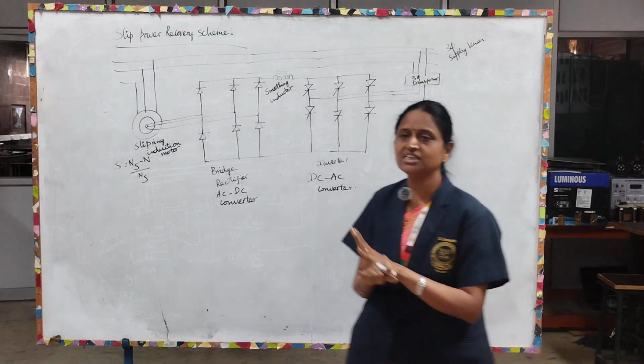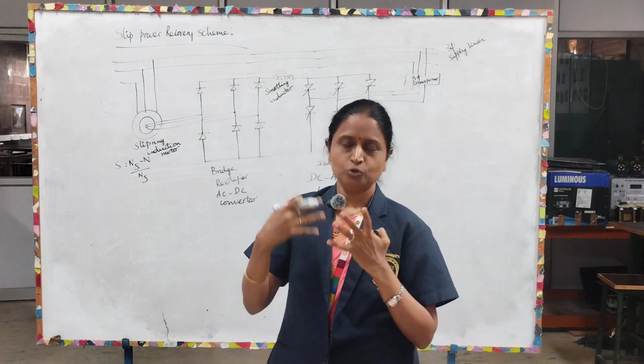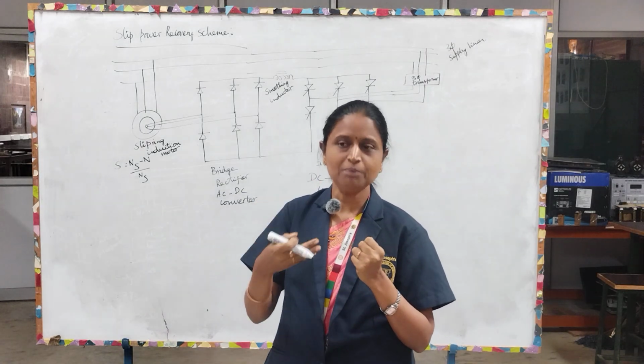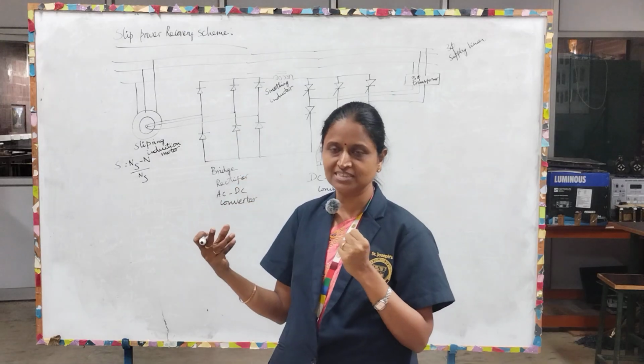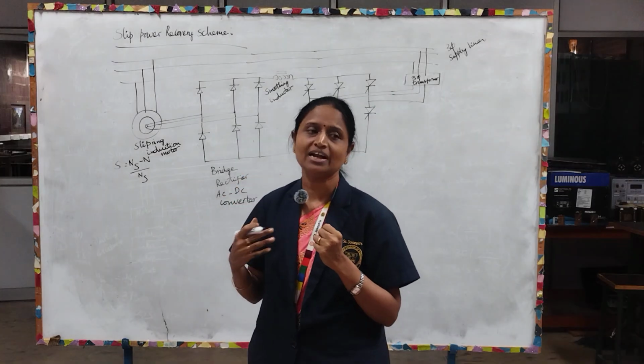So instead of wasting slip power, we are using it in an effective way. We are pumping the power back to the supply lines. That's why it is called the slip power recovery scheme.